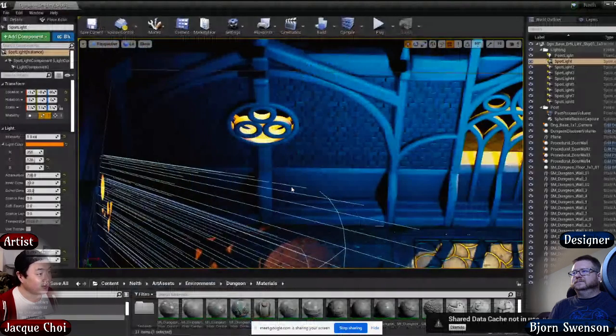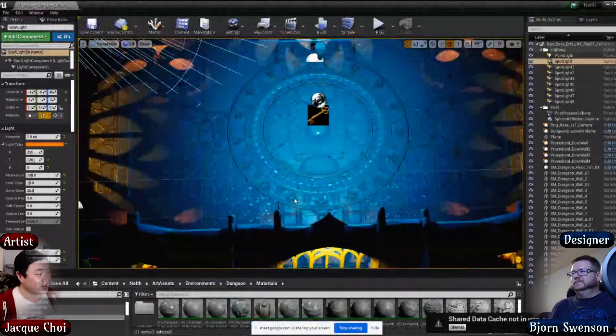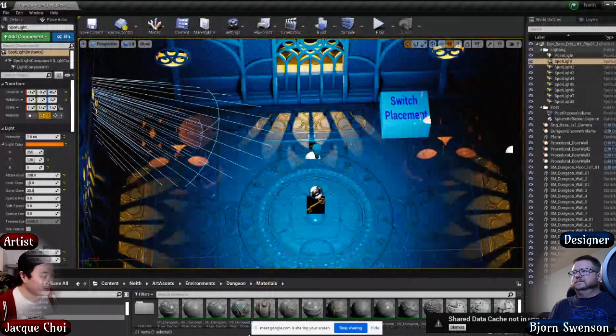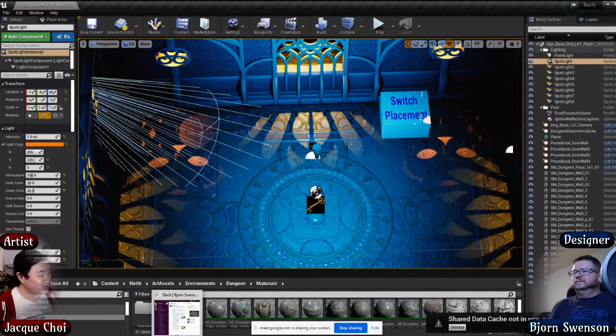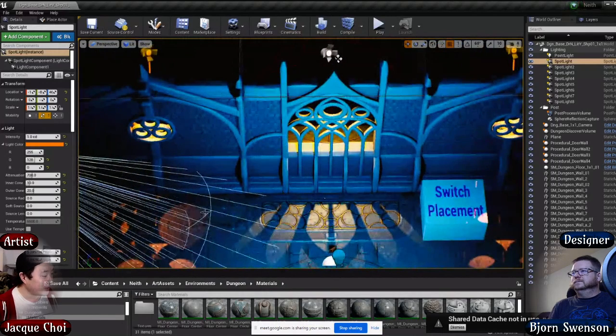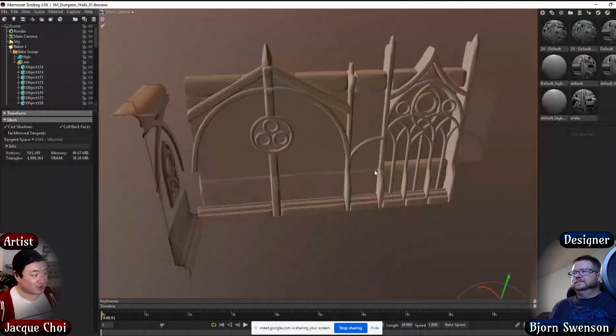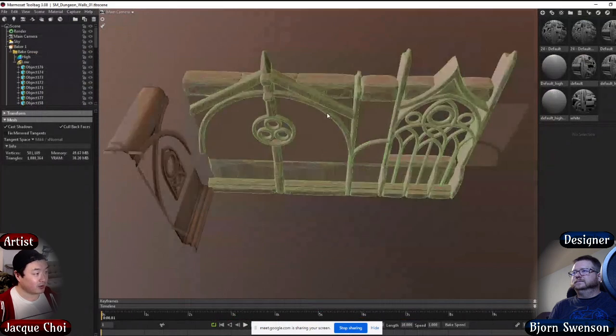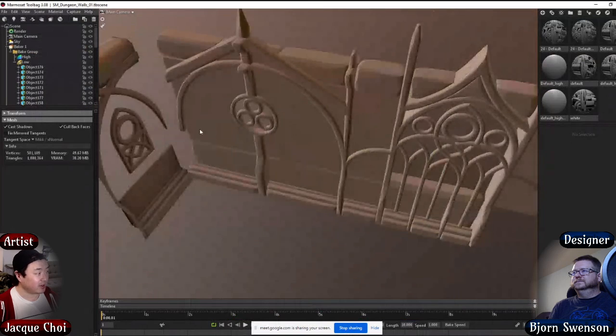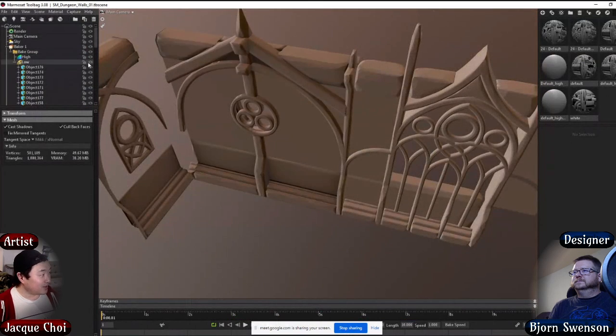It was actually developed by a former student of mine from one of my second classes. You pretty much just model your low poly and Boolean and do whatever you need to do with that, then you bring it into ZBrush, hit polygroups, Dynamesh, and then automatically smooth it. So you don't have to sit there and try to bevel and chamfer and figure out how things work, because usually that requires a lot of foresight. Whereas the way he works, it's just a messy mess. You can see this is going to be the brick area, and this is my high poly I whipped out last week, all three panes, and then I did the low poly based on that.